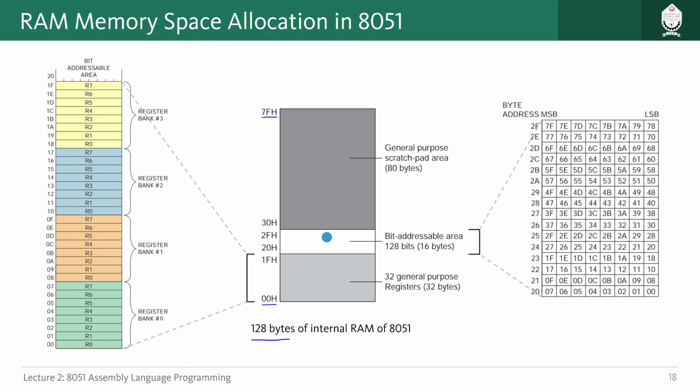So for those particular scenarios, we can use this region of 16 bytes. So they are bit addressable like that. Okay, all of the bits in these 16 bytes. So 16 different locations, and in each of the locations we have 8 different bits. So 16 multiplied by 8, in total 128 bits of memory we have. We can specifically address bit by bit.